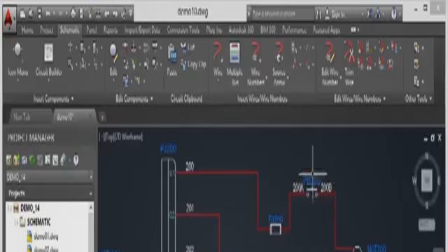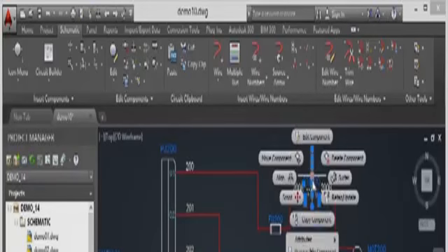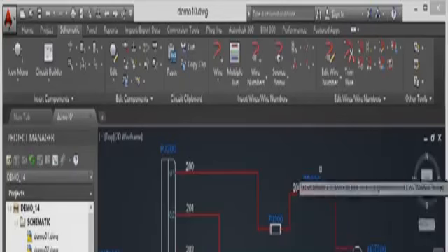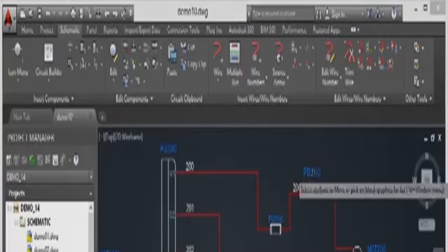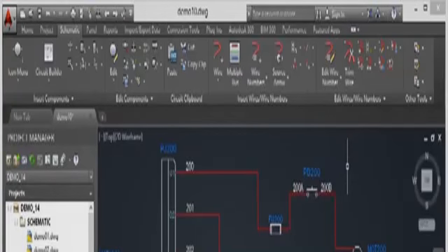What I might do there as well is I might select this PB200, right click, attributes, and move the attribute slightly. So I'll click on the PB200 there, right click, click there as a base point, just drag that up a little bit, and then just press enter to finish. And then we've got a nice retagged W block circuit in our AutoCAD electrical drawing.